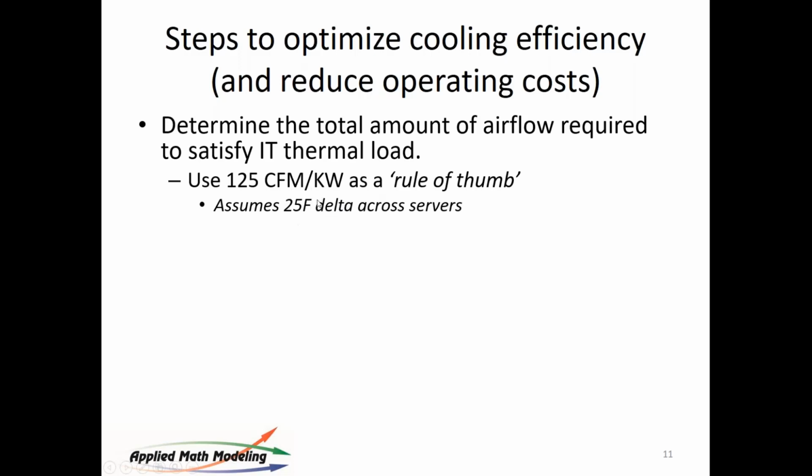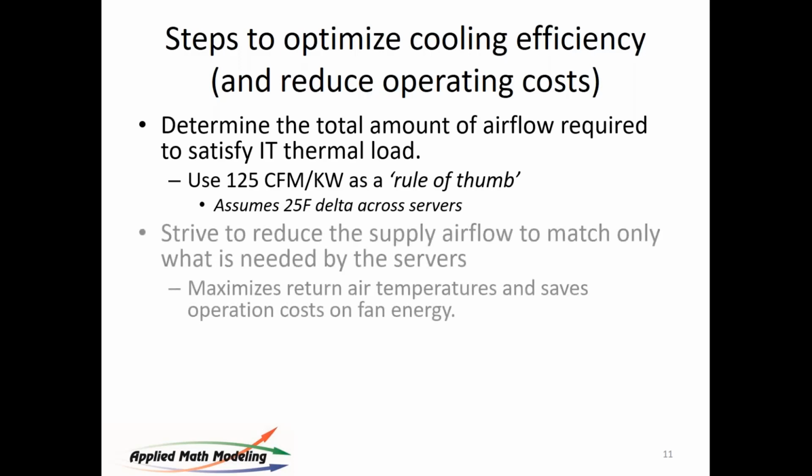We've moved that up a little bit in the most recent revision of CoolSim. We were assuming 20 degrees, and that number therefore was about 156. But servers are getting more efficient. There's a lot of sensitivity in the server world right now, in the design and manufacturing of these machines, to make sure that they're more energy efficient. They're using less fan. And so the airflow seems to be a little lower, and the delta Ts are getting a little higher.